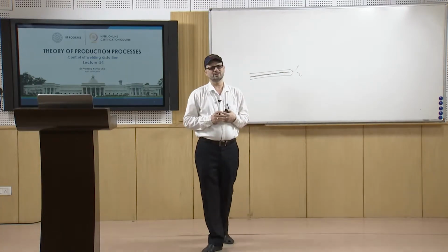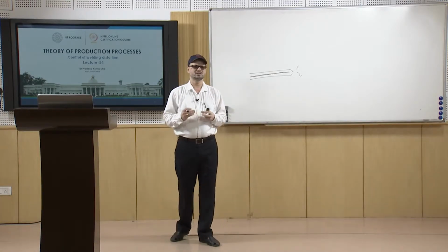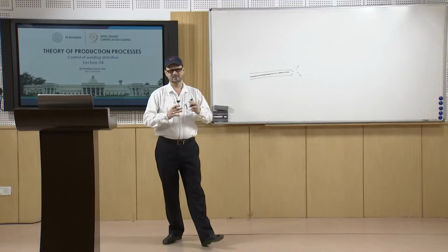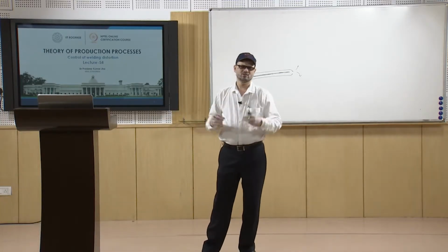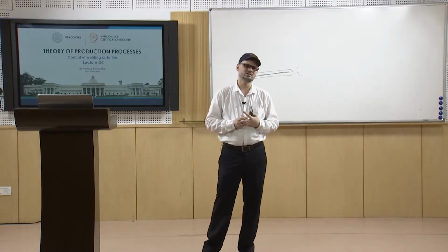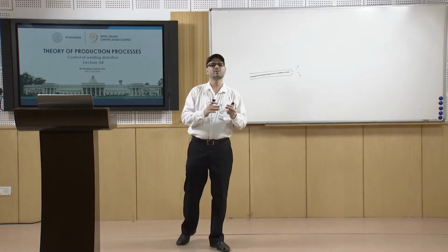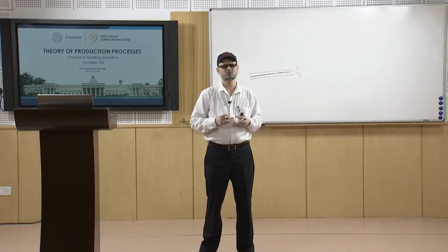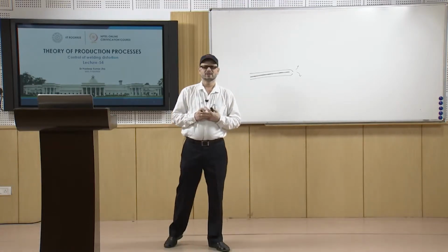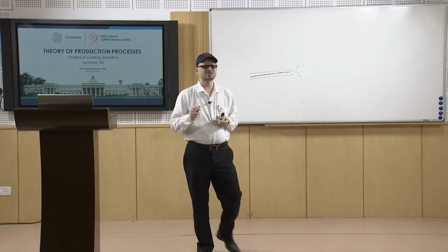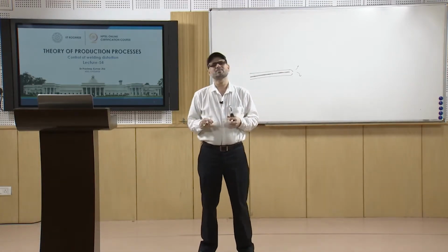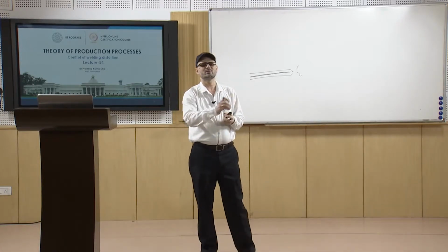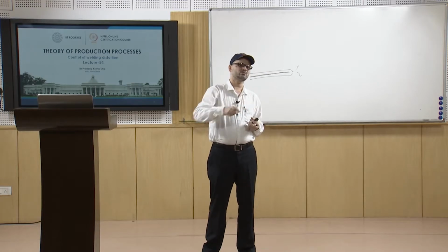Then you have welding sequence. Welding sequence means how you have to proceed in the welding. Suppose you have a particular type of welding structure, for example transverse welds or longitudinal welds, a plate type of weld structure, or a cylindrical type of structure which is to be welded. In that case, in what way you should proceed, whether the transverse welds should be welded first or the longitudinal welds should be welded first. There are certain defined steps which should be followed. Similarly, a backstep welding process is also there, where the welding should be in the backstep manner. So, backstep welding tells you how you have to proceed with the welding. In the longitudinal direction you have to go, but then you have to go in a backstep manner.